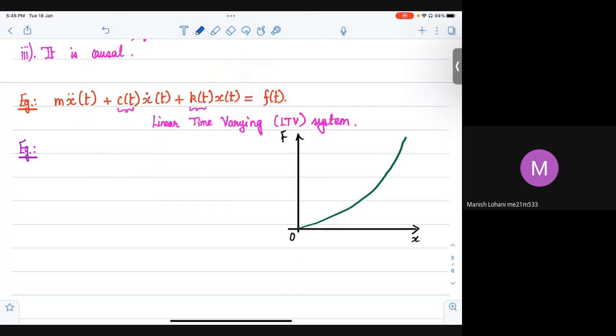What we typically do is that we may put the spring in a pre-compressed state, and our region of operation may be a very, very small region around this initial state. So then we linearize about this operating state, and we take the slope of the curve as our spring constant K and use a linear spring model, where the restoring force of the spring is K times X.